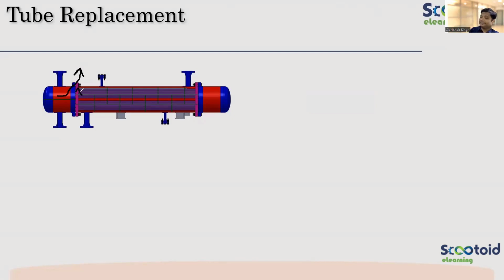Now it's clear. Okay, because in the tube side, you can see there is bolting, there is gasket. Those are prone to leakage. Leakage may happen, but once I have welded, the leakage will not happen. So that is where I'll like to use the fixed type. So if that is there, then I'll use that in shell side other than the tube. I'll not use it in tube side.